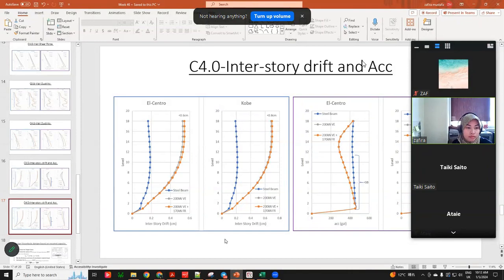I believe the short beam has a higher degree of coupling compared to the longer one, because with a longer beam you create a larger moment at the coupling beam. So if the beam is long, the two walls move somewhat independently, and with the short beam, the two walls move together.